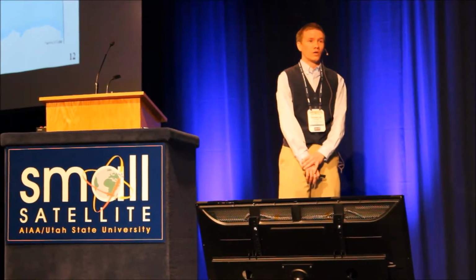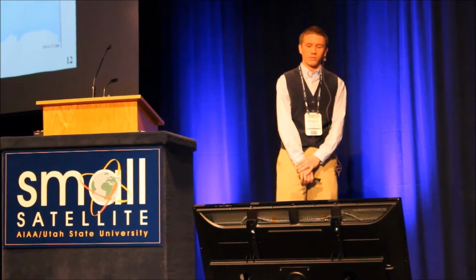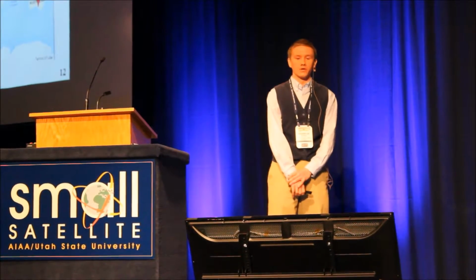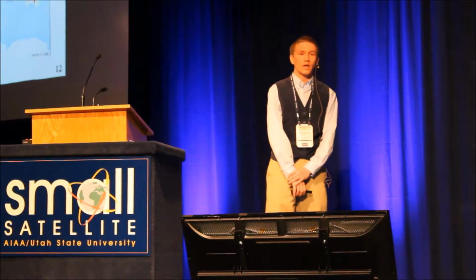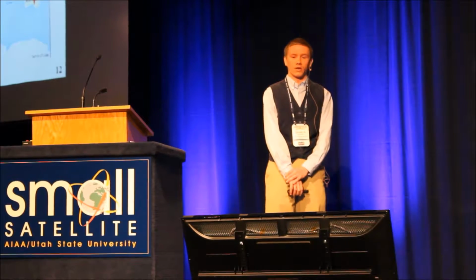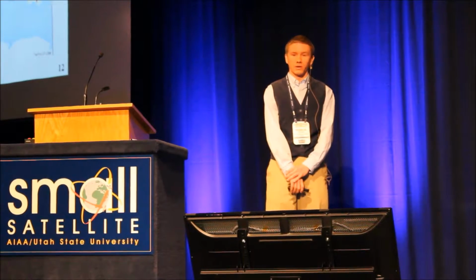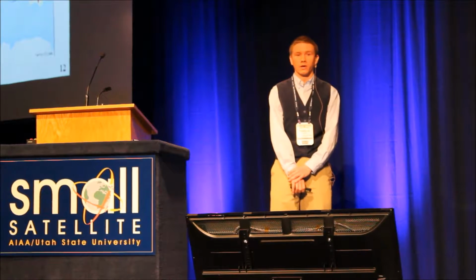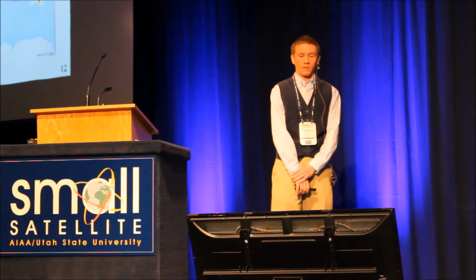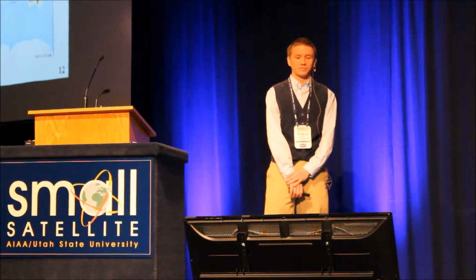24% of all of our data over the course of the mission was actually received in the form of the beacon, which illustrates the utility of making sure that all the fields in the beacon really are data that's useful to the operators. Our beacon was originally written as a day-in-the-life debugging tool, so it had some fields, for instance the health of the transmitter, that are kind of implied by having successfully received that beacon.